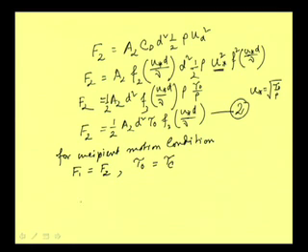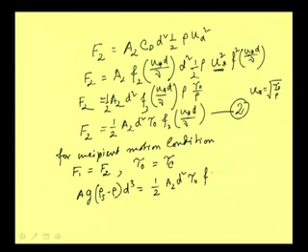So equating these two, we can write A1 g (rho s minus rho) d cube, this is the expression for F1, equal to half of A2 d square tau c, and f we have generalized, now it is a function of u star d by nu. Not tau 0 now, we will be writing it as tau c.